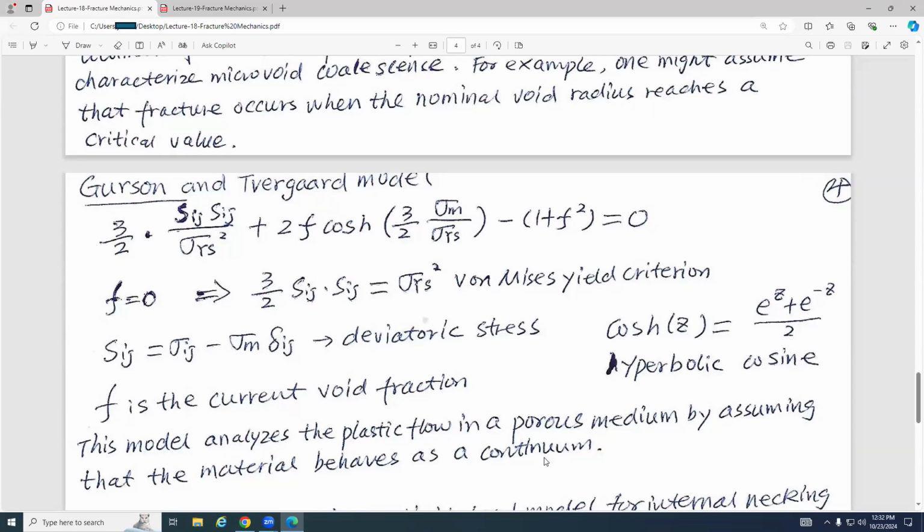So how does this equation work? If this equation is satisfied, that means the crack tends to propagate. What this equation says: you can see in this Sij, i appears twice, and in this other Sij, i appears twice too, so i is a dummy index, right? J is also a dummy. As I told you guys, a dummy index means summation, right? So Sij multiplied by Sij is a summation over all of these deviatoric stress components.